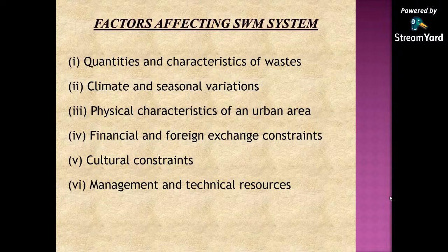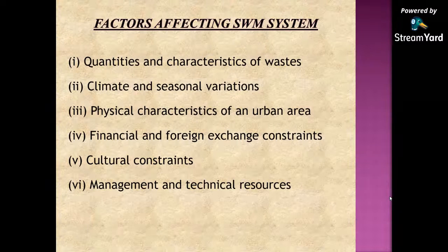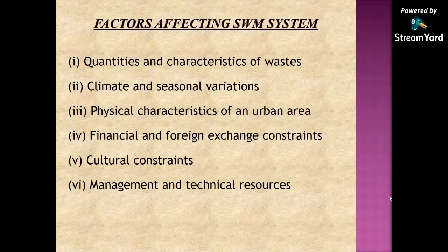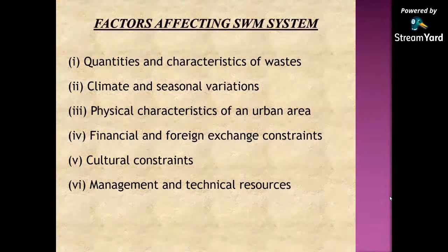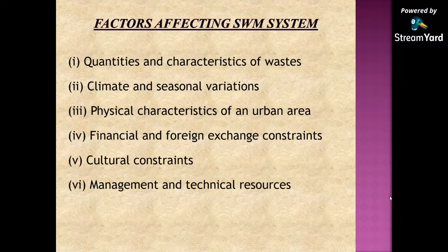The next factor which affects the SWM system is climate and seasonal variations. There are regions in the extreme north and south where temperatures are very low for much of the year. So in cold climates, drifting snow and frozen ground interfere with landfill operations, and therefore trenches must be dug in summer and cover material stockpiled for winter use.